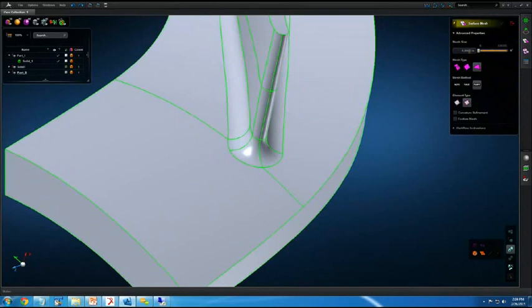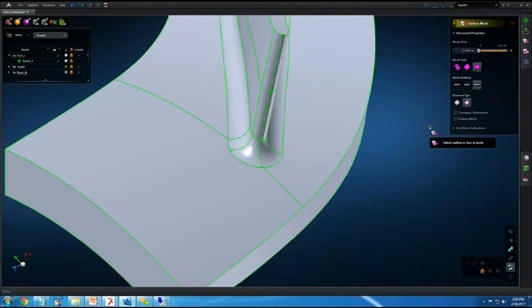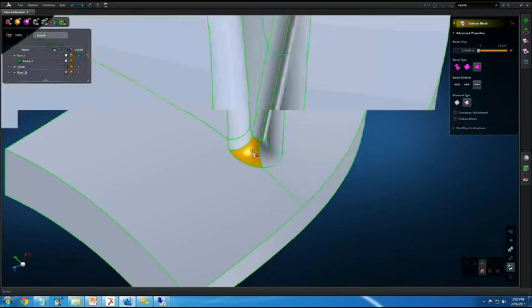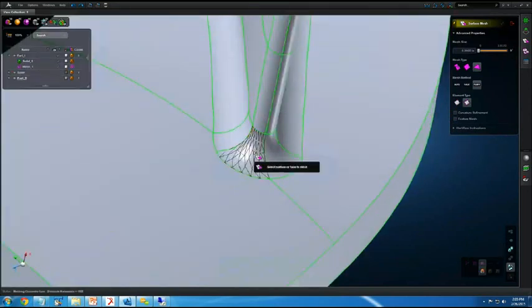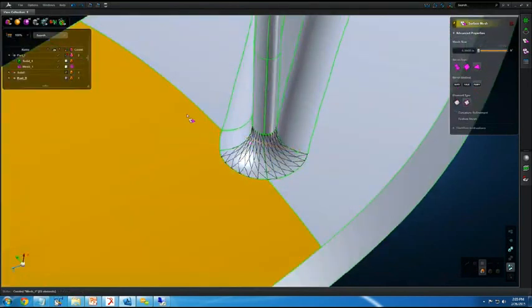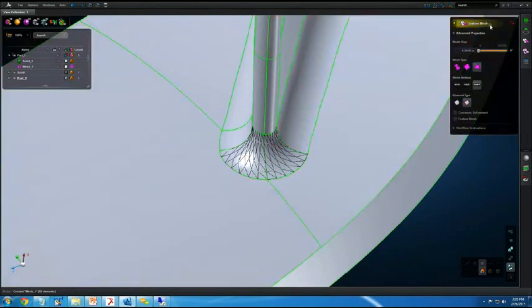Going to go ahead and stick with 6/1000 of an inch for our mesh size. Going to use triangle elements for our mesh type, map mesh, and quadratic elements. Okay. Go ahead and select face as well as this one. Close out the surface mesh tool.